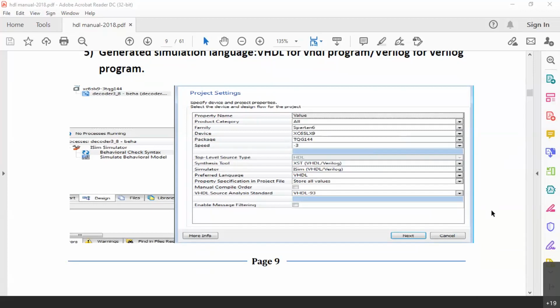So let us say this particular chip has 144 pins, out of which 44 pins are power supply and ground. Now the remaining 100 pins, all these pins are programmable. Whichever we want to be input, whichever we want to be output, we can select it that way. That is the beauty of FPGA.